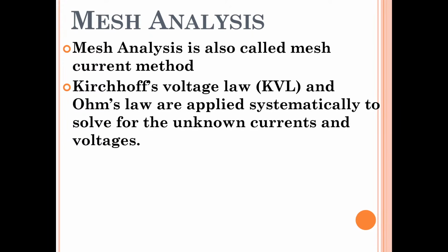So mesh analysis is also known as mesh current method. This mesh current method is a network technique where mesh or loop current directions are assigned. Then, using Kirchhoff's voltage law and Ohm's law, they are applied systematically to solve for the unknown currents and voltages.